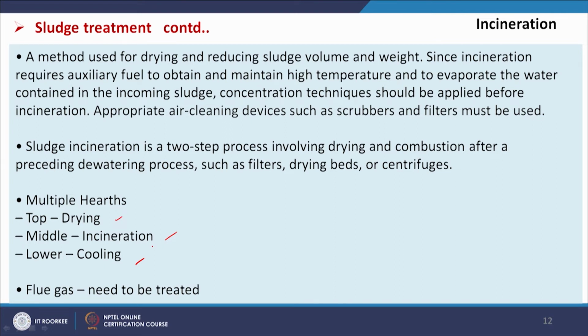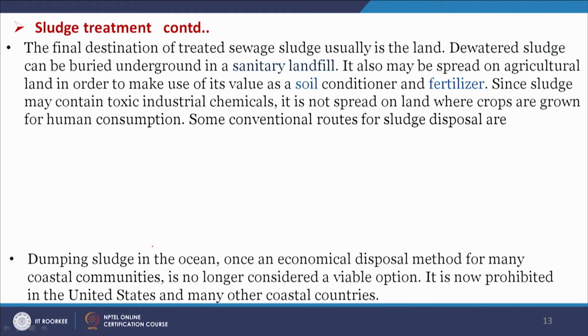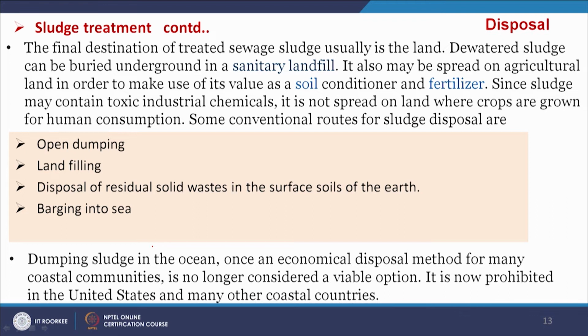So, this is the incineration, and we will have a detailed discussion on incineration in solid waste management, and the same methods are applicable for the incineration of sludge also. Now, we are coming to the disposal part. The final destination of treated sludge is usually the land. Dewatered sludge can be buried underground in a sanitary landfill. It also may be spread on agricultural land in order to make use of its value as a soil conditioner